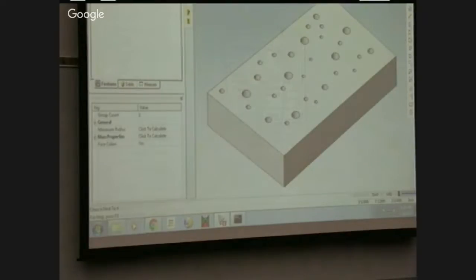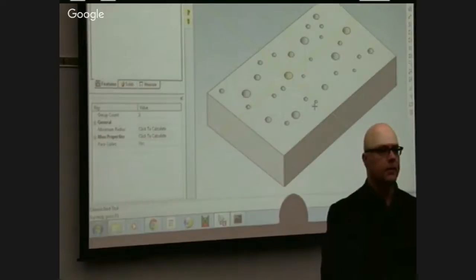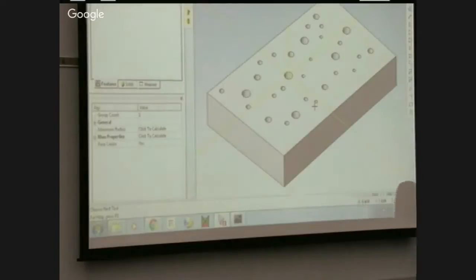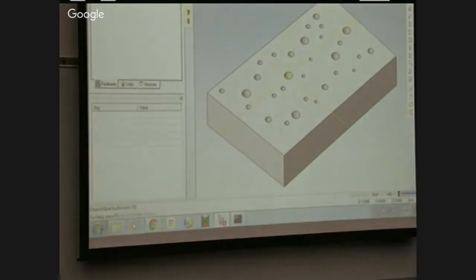Now I could edit, move origin point, and I can put it at the midpoint of one of these lines. I can put it at the midpoint of one of the features. What if I wanted it to be the midpoint of the block? Well, what if I want to use move origin to do it? I can go draw a line between 2 points.